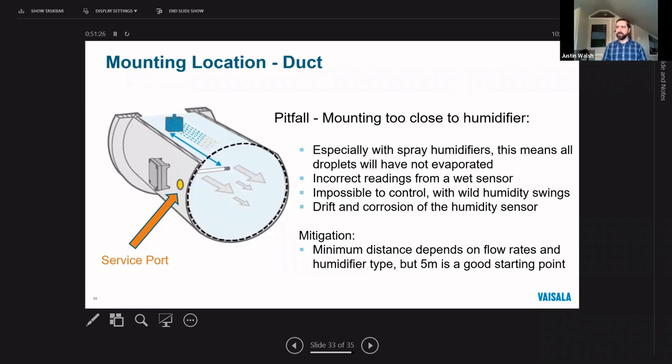And this is for 2 reasons. The obvious one is that the sensor can get wet and stop reading accurately. It won't read accurately until it dries out. The second is that if the sensor isn't getting wet, it's not measuring the water vapor from the condensed water droplets. Either way, a proper reading is impossible, and the system will use more energy to balance the desired space conditions.